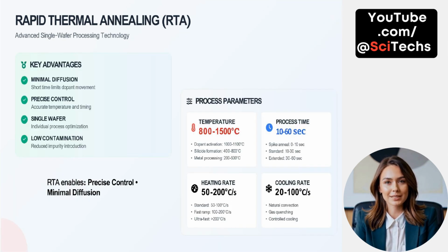Rapid thermal annealing, or RTA, is a crucial single-wafer processing technology used to enable precise thermal treatments in semiconductor fabrication. One of the biggest advantages of RTA is minimal diffusion. Since the wafer is exposed to high temperatures only for a very short time, dopant atoms don't have much time to move, preserving junction depth and profile.